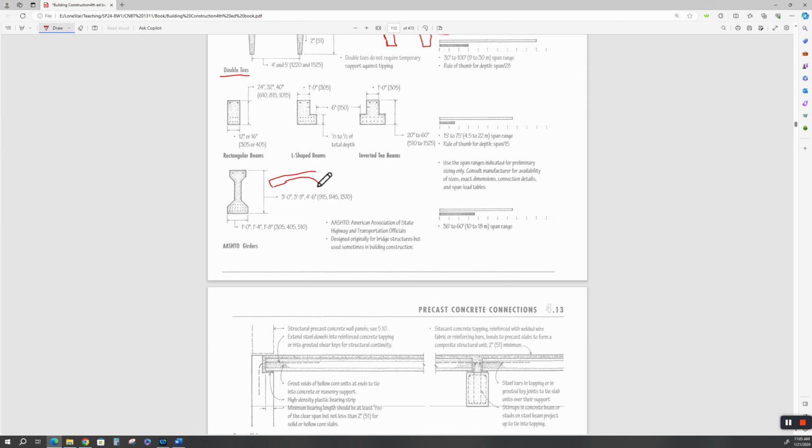They were bent up a little bit. Well, not like that, but they had a little bow in them going up. So when they laid them across and started putting the road deck up there, these things flattened out. And they had construction engineers monitoring how much deflection, to make sure that they deflected exactly the way they were supposed to. This was all calculated by the structural engineers. Again, here's a rule of thumb for those spans.